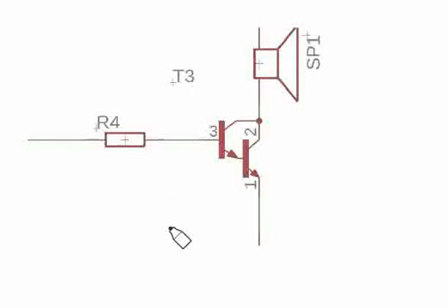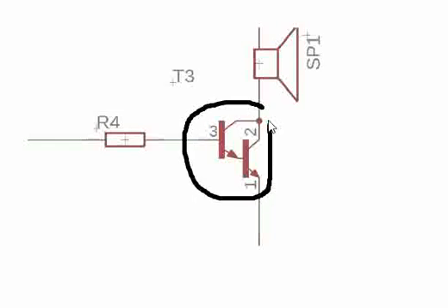This circuit shows such an application, where this is a Darlington pair circuit, and you have a speaker which is connected between the collector terminal and the operating voltage at the collector side, and then you drive your circuit from the base.